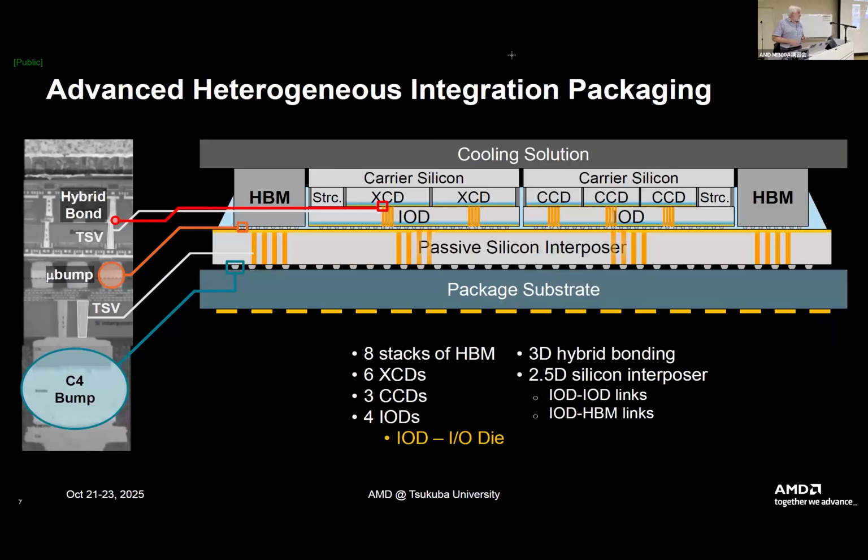And here's a diagram showing what's happening here. So you have this silicon layer there, and they're placing the chiplets on it. And this is transforming what used to be a 2D architecture, where we had all these pins down below trying to get up into the chip. Now we have a 2.5 or 3D architecture with silicon vias going through the different layers.